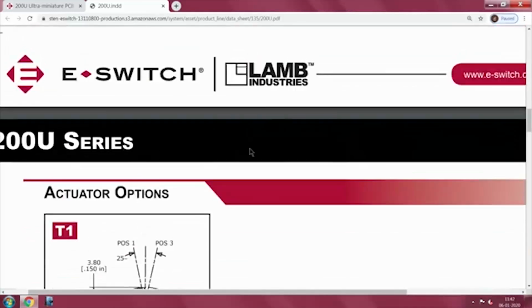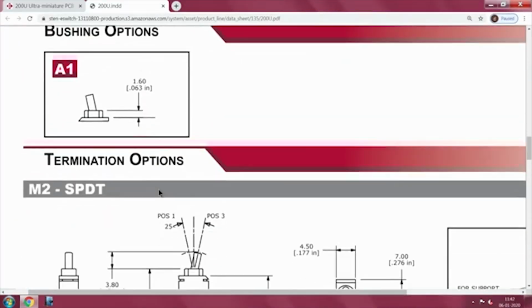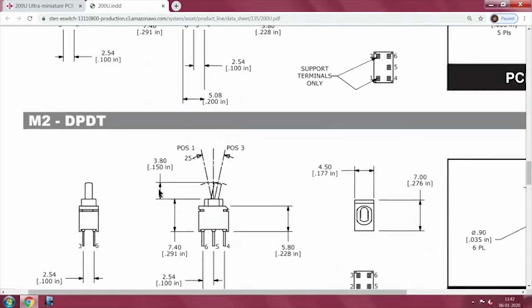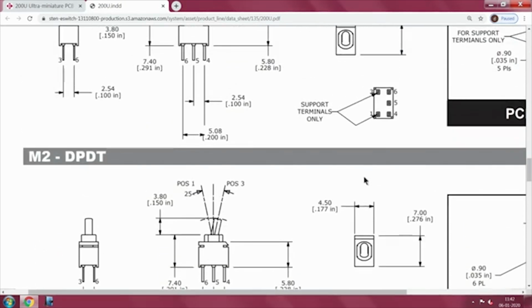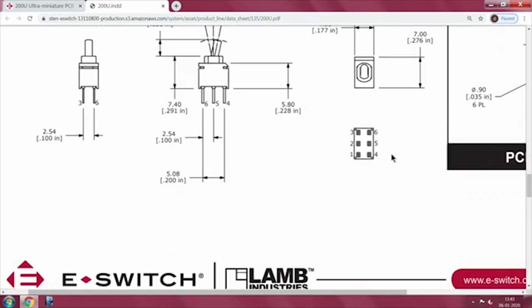So, they have given, if you see the options here, for example, here we have the single pole double throw, next one is double pole double throw, good enough. Now you come to the other thing, then what happened to the support terminals? You see here in this case, that same thing is used for support terminals. Why this is in general from a mechanical point of view, unless at least two of the terminals are mounted as far apart in the corners of the unit, chances are it will get damaged.